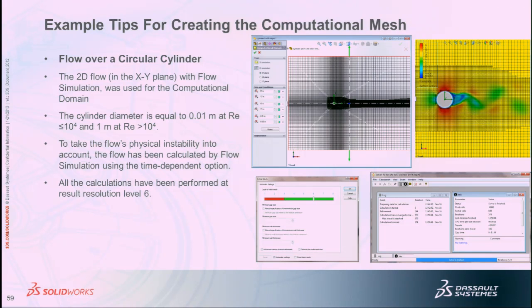And it remeshes it, and then it starts up again where it last stopped, and continues the solution. And whether you have 6, 7, or 8, it'll do it more times. So at 7, that might happen 2, 3, 4, 5 times, depending on the internal criteria, whether it requires more. And so you can see in this particular case, the adaptive refinement was basically in this general area, and you can see it kind of tapering off down here because the gradients are becoming more centralized within this particular model.